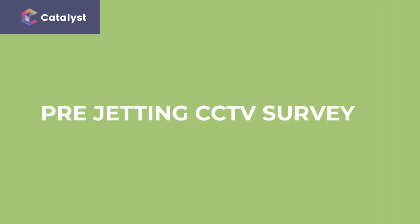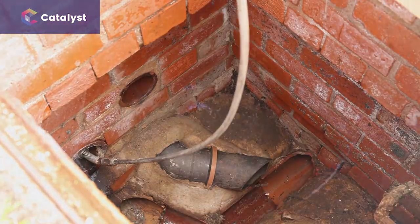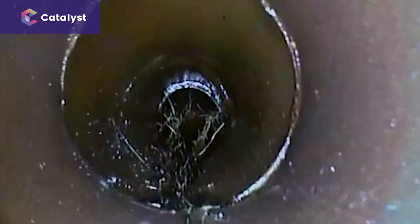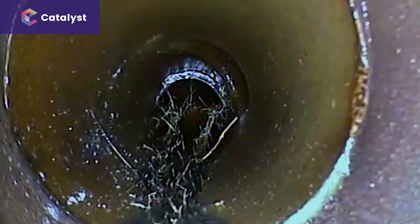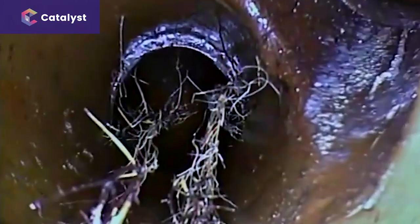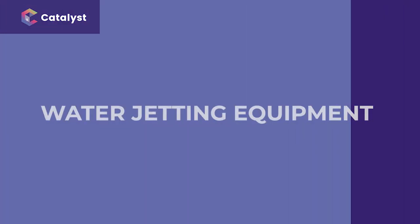The engineer introduces a camera into the rodding eye of the drop shaft. He first tries to carry out a survey without cleaning the pipe. This is to see if a blockage, especially in the surface water pipe, is causing a leak further up the system. If jetting was carried out first, this detail would be lost. In this case, it's clear from the number of roots and other materials in the pipework that water jetting will be needed. Before we start jetting, let's have a look at the jetting equipment and explain what it does.